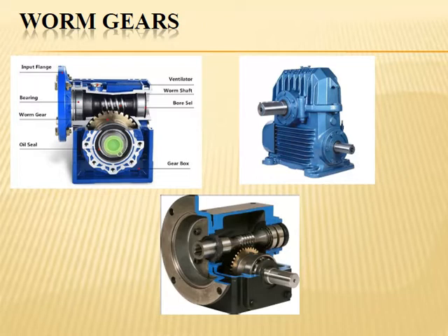While selecting a lubricant, we must select a lubricating oil of sufficient viscosity, which will enhance the development of a suitable oil film between the two tooth surfaces and sustain the oil film under the load.